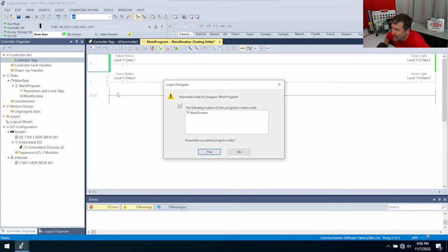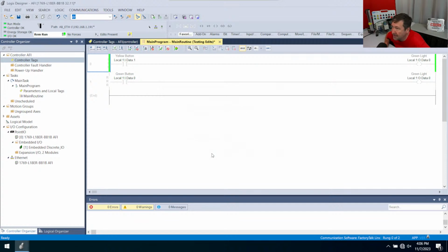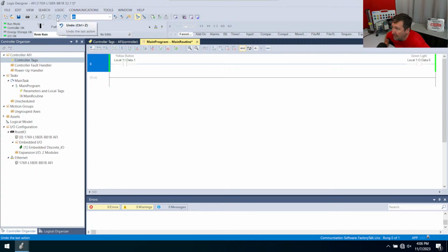What this is going to do is tidy it all up and delete the old. And watch this undo button as I do this. Notice it's grayed out now. We cannot undo once we do that final step. And that's why I want you to understand the 3 steps before you start just using the finalize button.